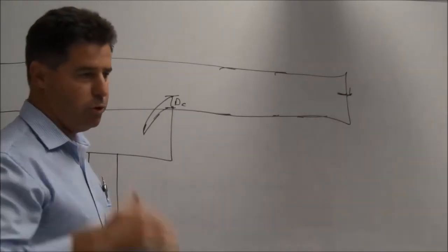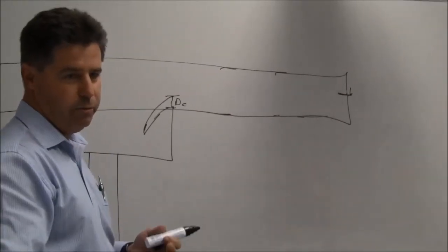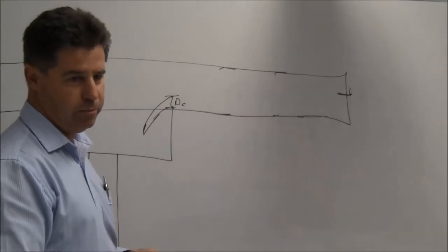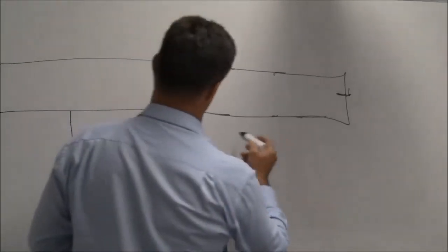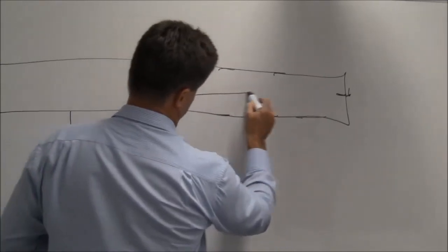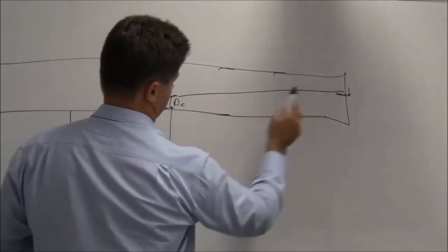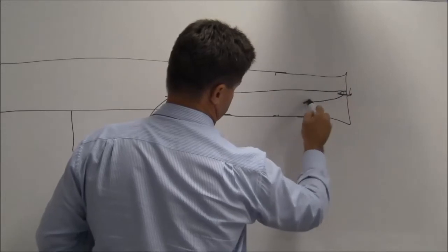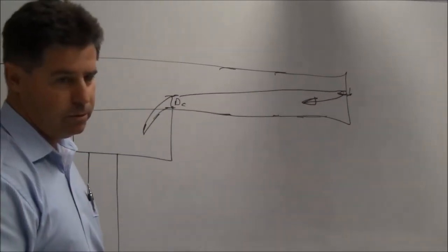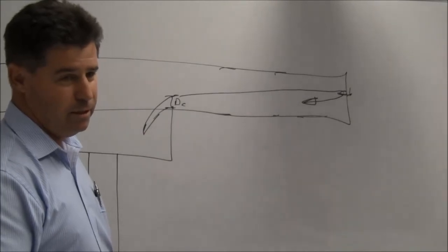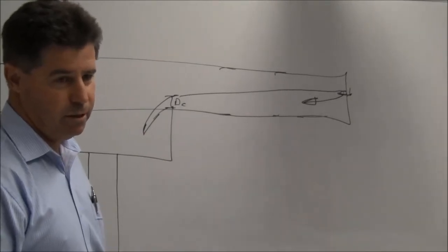To force water to get it moving, we need to create head over it, to move a mass. Because water obviously has weight, so we need a mass. So basically, all we do is multiply it by 2 for this critical depth, which gives us our head of water to actually force it towards the actual sump. Does that make sense? That's the easiest way to explain it.